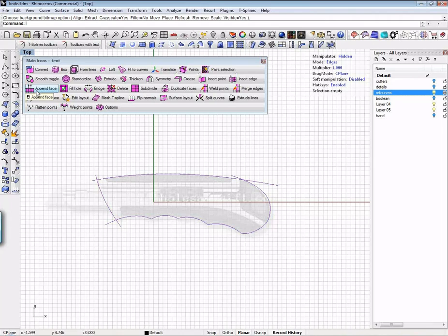The last couple of tools I want to show you is this append face tool. And what this allows you to do is make a four-sided single face. Pick three corners and right-click, and it'll make a face. And now what I can do is, going back using that Alt-Drag workflow, I can set my mode to edges up here. I can pick this edge. I can bring up my translate manipulator, and I can Alt-Drag this edge out.